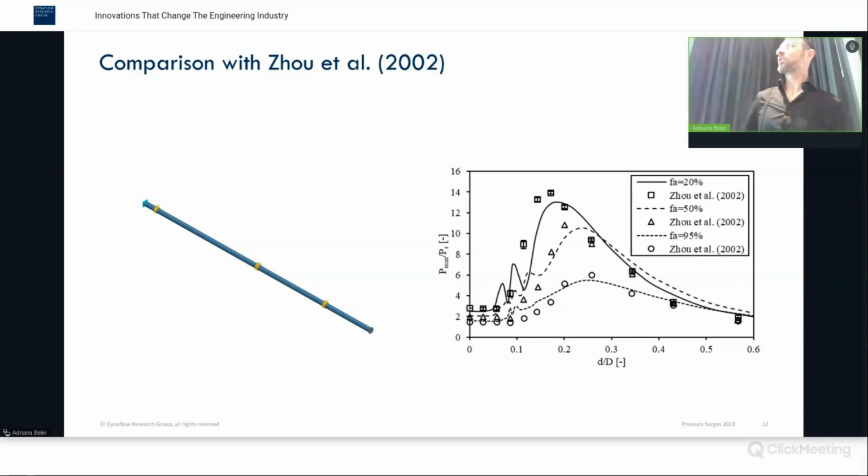So this is all available in our commercial software package called Boss Fluids. We don't model the entrapment of air bubbles in the liquid column as it goes through the system. On one sense, that's fortunate because you get conservative results, because a higher wave speed results in higher pressure surges. But of course, it can be a little bit too conservative. So this is something that we're still working on and trying to see if we can improve on that.